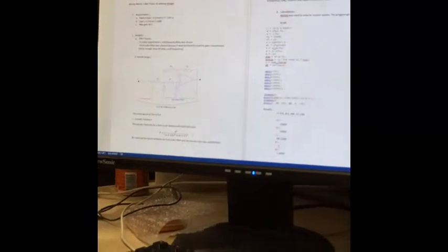And then we want to have a gain of 2 at DC. We also want to have our corner frequency be 200 hertz, so we'll have a gain higher than 0.9 at 200. And over 1,000 hertz, we want to have a gain of less than 0.1. So we picked a third order Butterworth filter to be the kind of circuit we wanted to implement. If you come here, the transfer function that we implemented is this, right here.